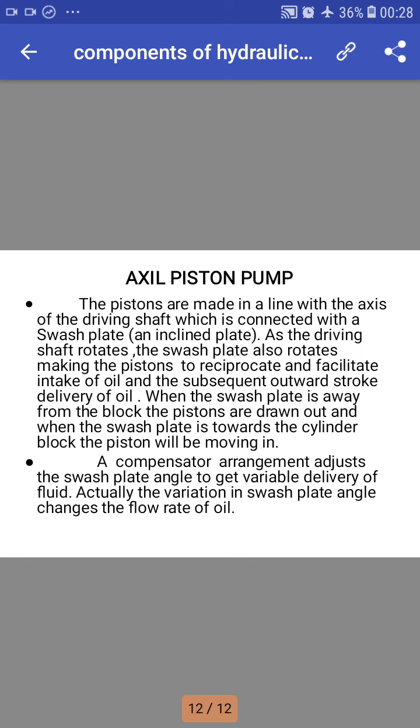When the swash plate is away from the block, the pistons are drawn out, and when the swash plate is towards the cylinder block, the pistons will be moved in. A compensator arrangement adjusts the swash plate angle to get a variable delivery of the fluid. The delivery will depend on the angular position of the swash plate. Actually, the variation in swash plate angle changes the flow rate of the oil.